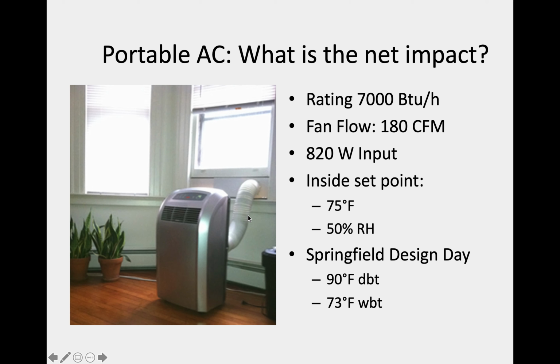Now, they usually only have one tube or duct that goes to the outside. And that means that they are taking conditioned inside air and blowing it outside. And unless the house is collapsible, that means that outside air is going to get sucked into the house by that exhaust flow. And the exhaust flow is not small.